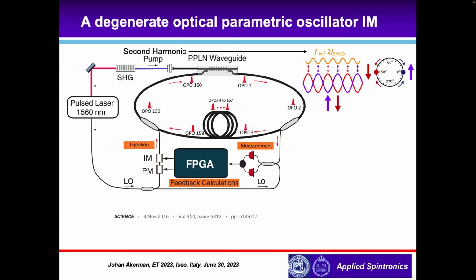So their spins will be optical pulses with a phase state. And then they siphon off a little bit of energy here and detect the phase, and let the FPGA store that in a vector of the phases. The FPGA has the matrix for the matrix vector multiplication, and then you get out what the element should be that you should feed back to a particular pulse when it passes through the second nonlinear element. So then you add energy in or out of phase with that pulse in proportion to the result you got from that matrix vector multiplication.